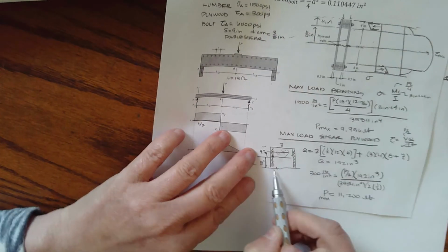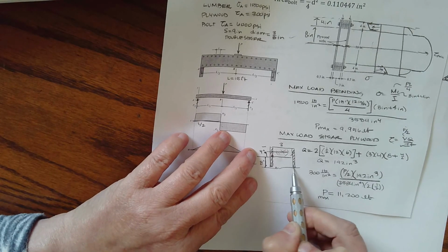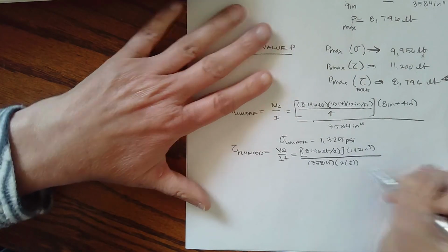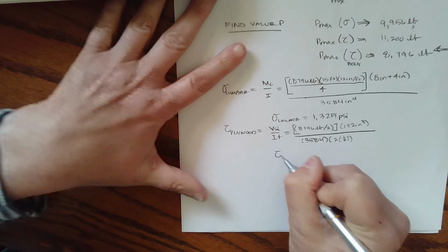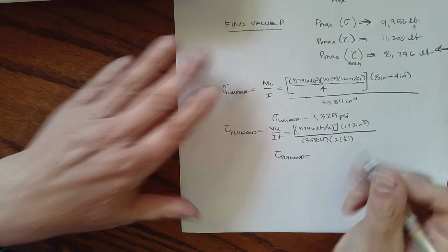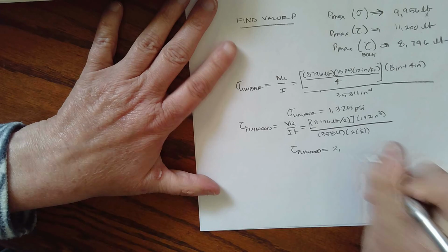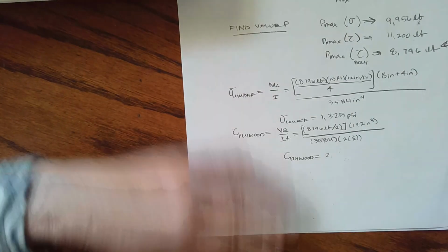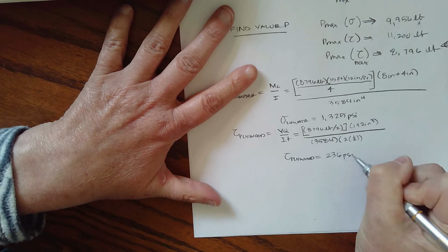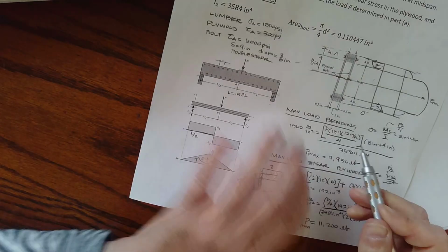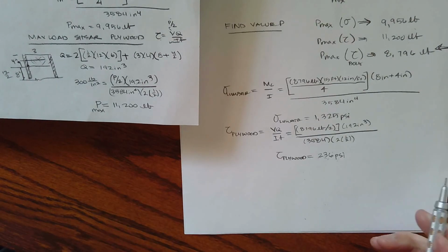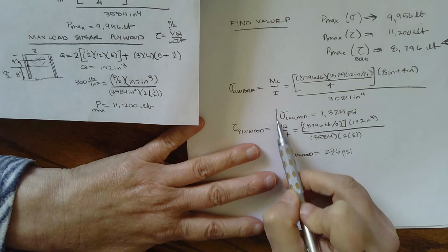And remember, we found it was a 1/2 inch plus a 1/2 inch, 2 times 1/2 inch. And our shear stress of the plywood equals, not 2,000, it's much smaller than that, 236 PSI. And again, that's less than our yield of 300 because we weren't limited by the plywood, we were limited by the bolts. So everything else is going to be less than.